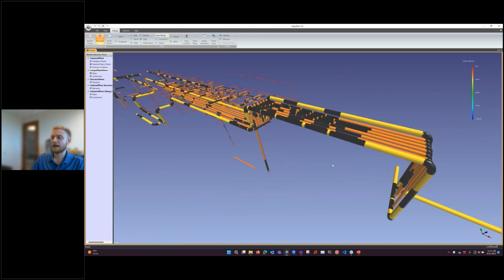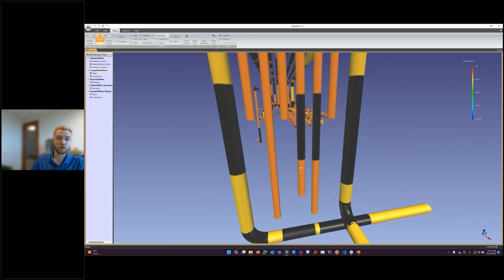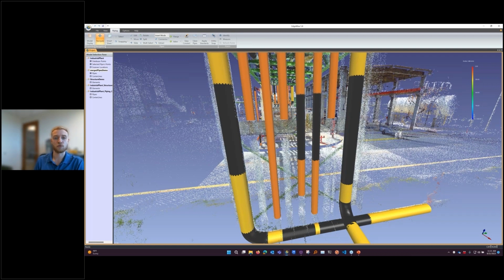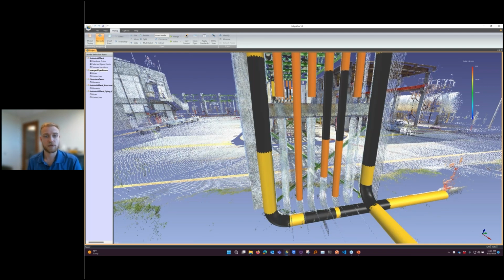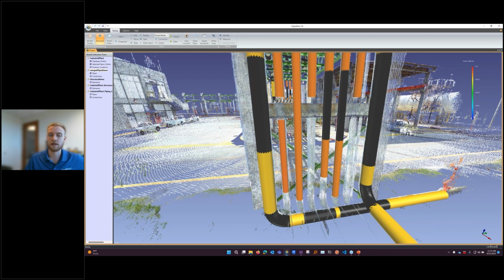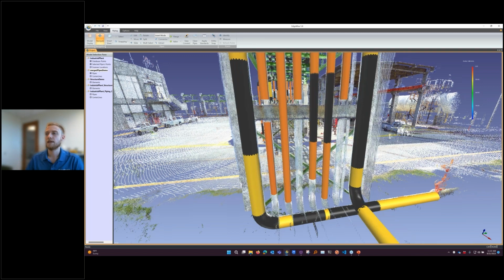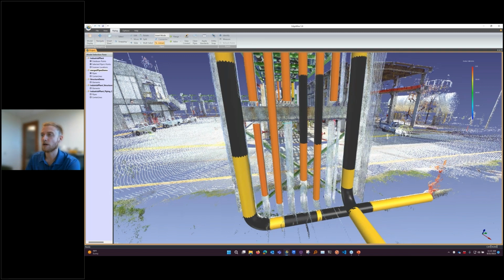We also have some manual tools, and these are really valuable for filling in that process. Everything we're looking at was just one-click automation. The other things we have are these semi-automated modeling tools that are also very much purpose-built for extracting geometry from the point cloud accurately. To create these cylinders that were not done automatically, I can extract by just drawing a box around the group of points that represents the pipe I want to extract. The software looks at those points in that zone I just selected. It's going to try and figure out the best size and position of that cylinder.